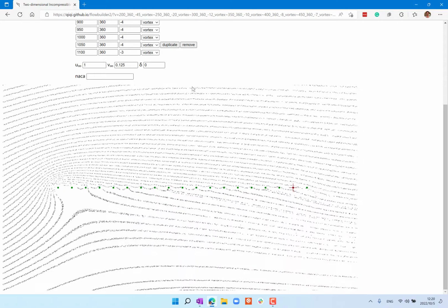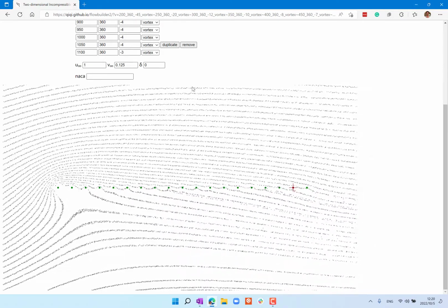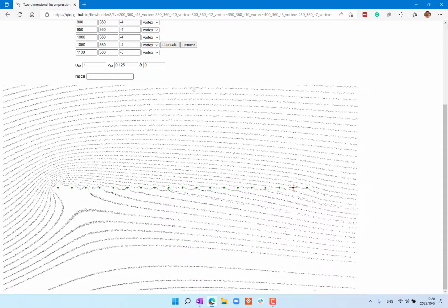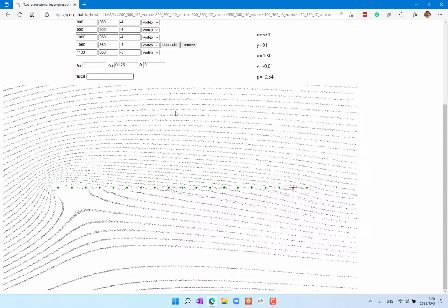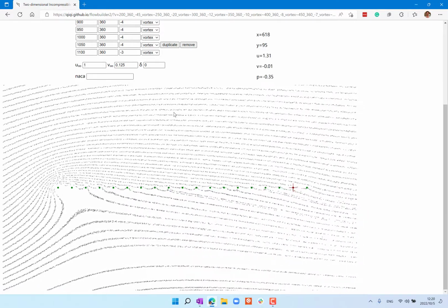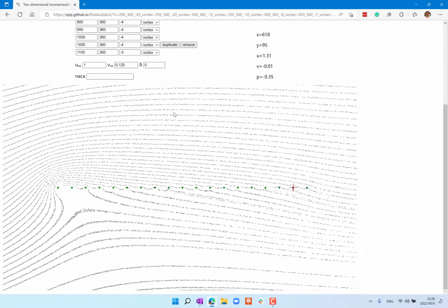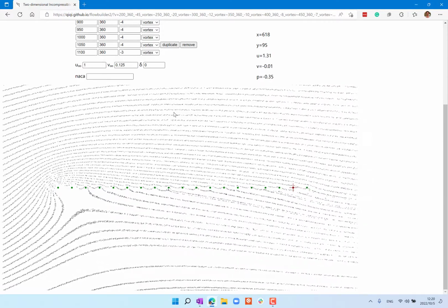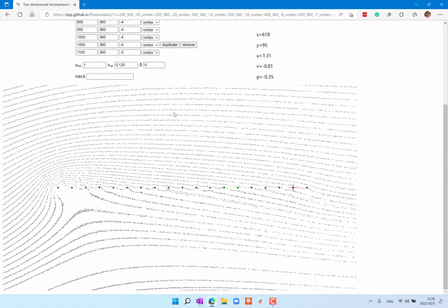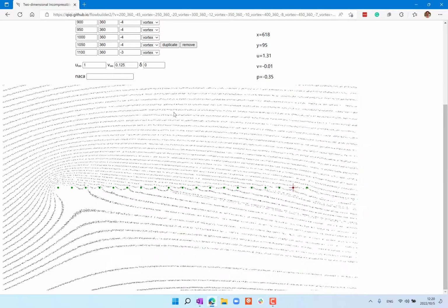So it's linearity. That means if I increase the angle of attack by a factor of 2, the lift increases by a factor of 2, right? Because the strength of the vortices, as you remember, affects the difference in the flow velocity up and down. If I increase the strength of the vortex by a factor of 2, I increase the difference in flow velocity by a factor of 2.